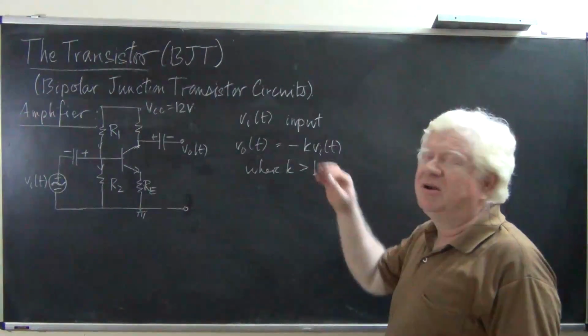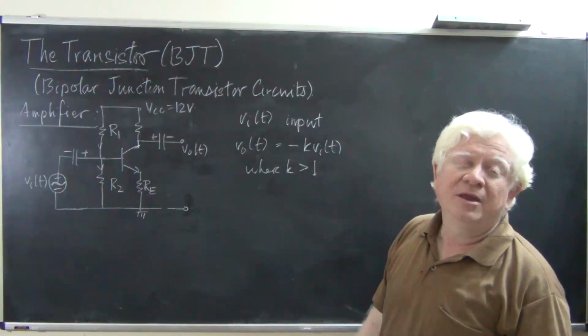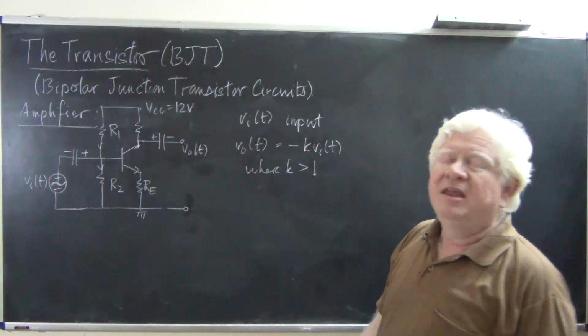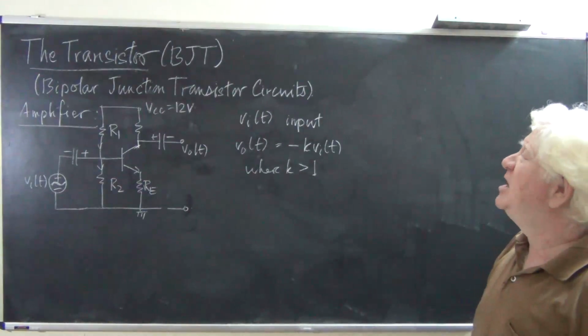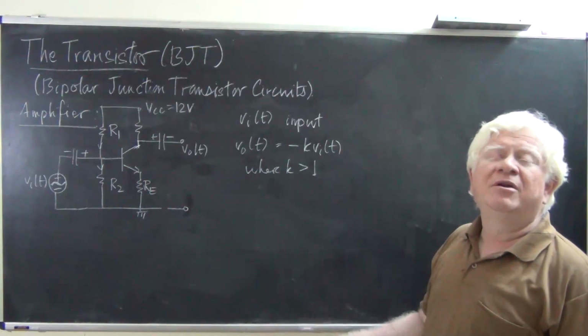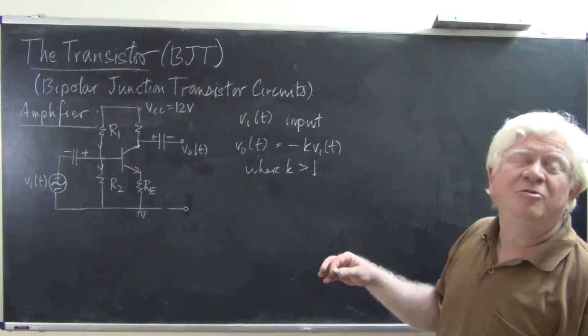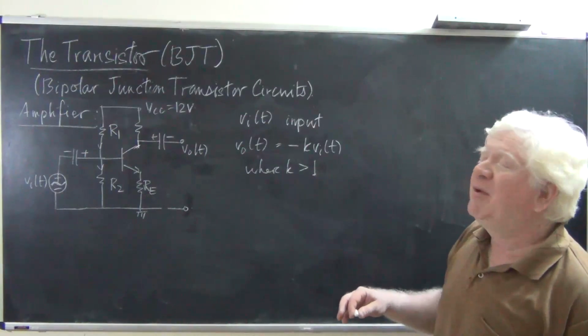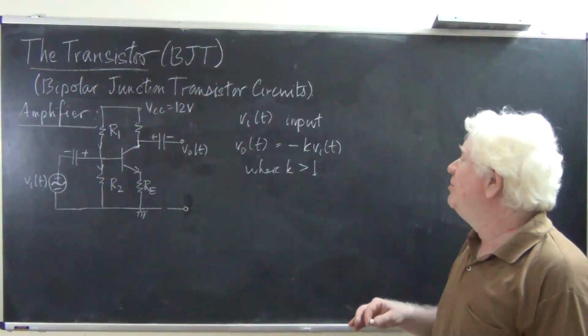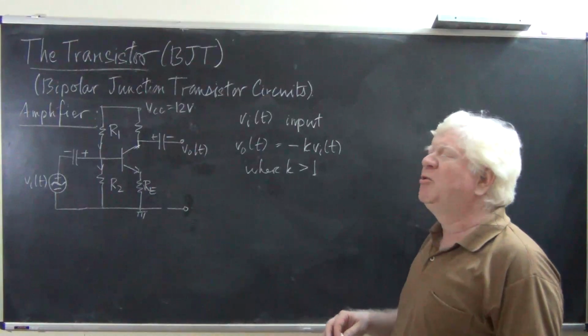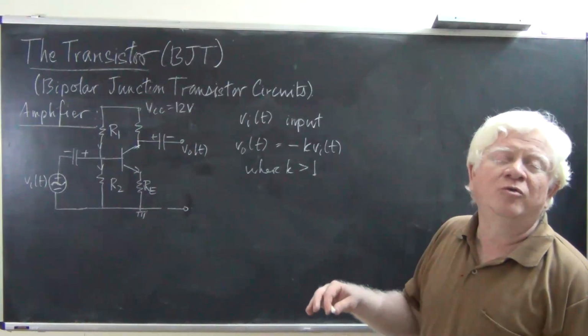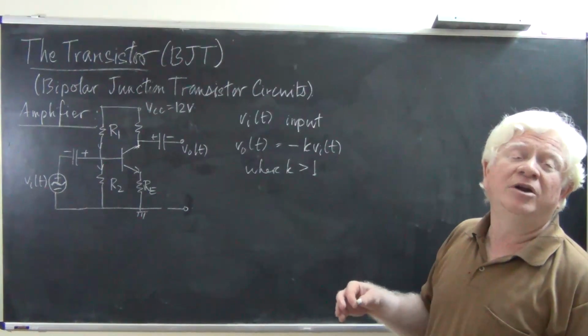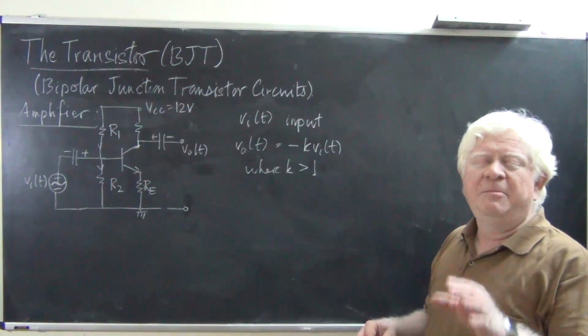The output voltage, even under the largest input voltage swing, should never really touch VCC. It should be slightly below that to prevent its getting distorted. For the same reason, the output voltage should never really go too close to VCE sat, because that again would lead to distortion.